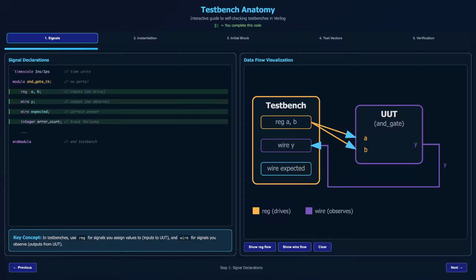And the tool that makes simulation meaningful and practical and possible is the Verilog code that surrounds your design in simulation. It drives inputs, observes outputs, and checks whether the design behaves the way it should. And the better your test bench is, the faster you can find problems, fix them, and move on with confidence.